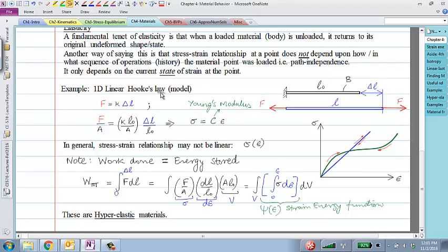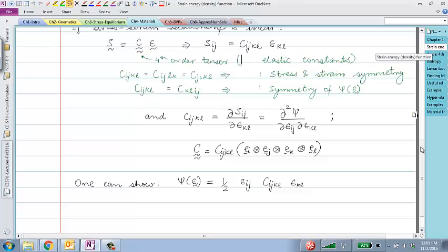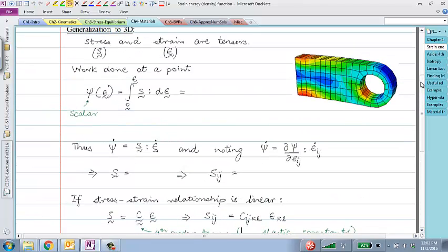The material model you've been predominantly using till now, Hooke's material model, is a type of hyperelastic material model. The whole idea is that in these types of models, if we do work on the material, it stores energy, and we can express that energy as a density function, meaning each and every point has some energy stored, and we are going to try to write what that stored energy density function would look like.